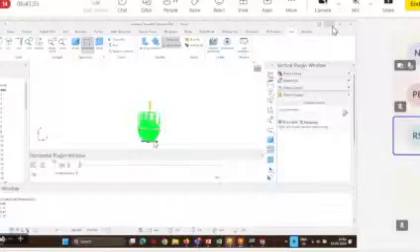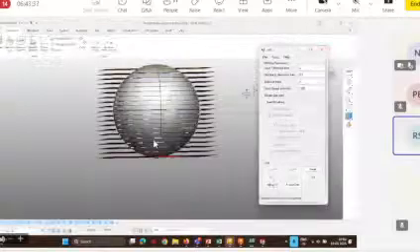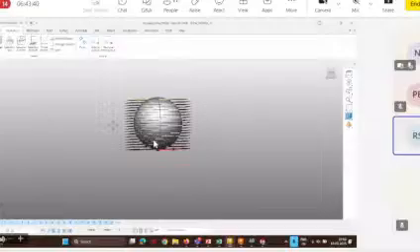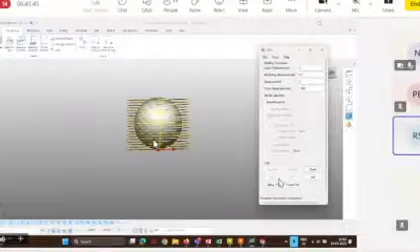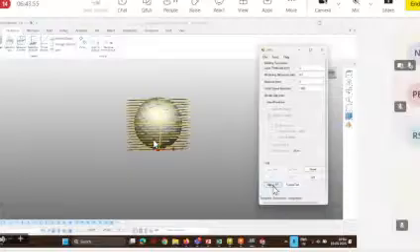But if you want to make some overhang structure, like maybe this sphere only, first I'll exit this one. So I will come back to here. Once this toolpath is done for the deposition, next I can generate toolpath for milling as well, because like I showed before, extruding the offset contours, based on the offset model, we can generate machining toolpath for getting the final finishing shape. So this is possible over here.